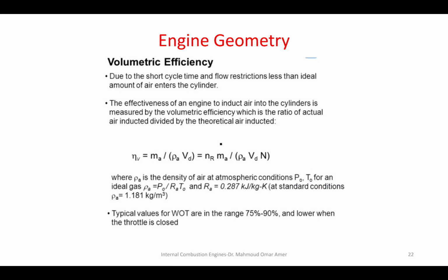So, here comes the term volumetric efficiency, which calculates the effectiveness of the engine intake. How do you calculate it? You calculate it as the actual mass that went inside the engine over the theoretical mass that should go inside the engine. The theoretical mass is Vd times the density of the air, and the actual mass is measured.